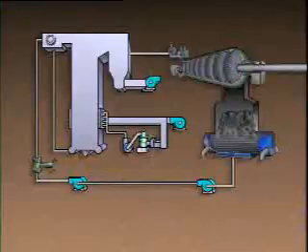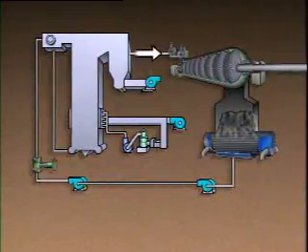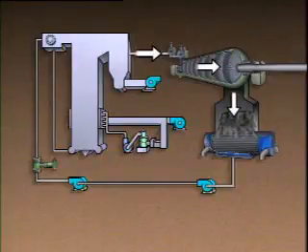Steam flows from the boiler to the turbine because of differences in pressure. Steam, like any other gas or liquid, moves from areas of high pressure to areas of low pressure. The steam pressure is at its highest as it exits the boiler. The high pressure in the boiler pushes the steam out through the main steam line, through the turbine, and into the condenser. As the steam gives up its energy in the turbine and is converted into water in the condenser, the pressure drops dramatically.